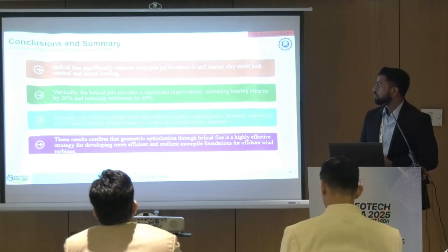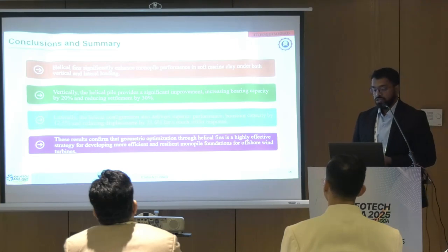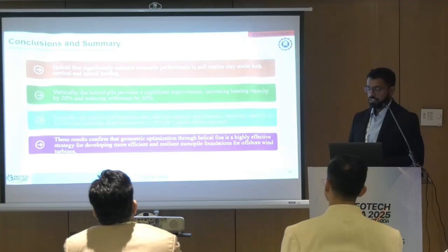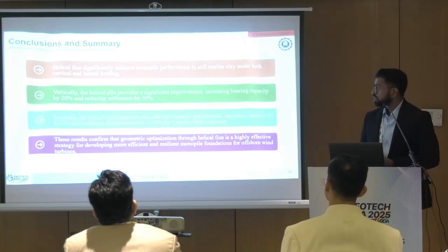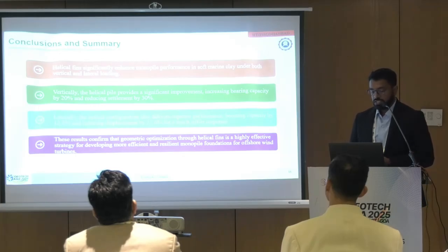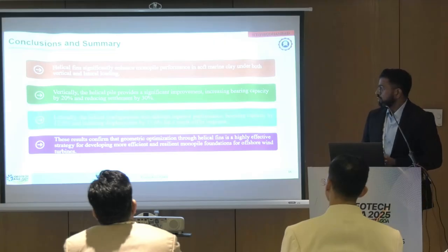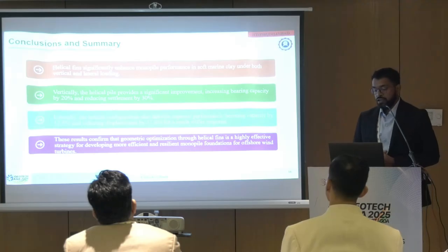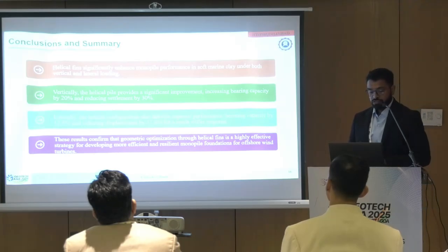2022. Coming to the conclusion and summary, helical fins significantly enhance monopile performance in soft marine clay under both vertical and lateral loading. Vertically, the helical pile provides significant improvement, increasing bearing capacity by 20% and reducing settlement by 30%. In the lateral direction, the helical configuration also delivers superior performance, boosting capacity by 12.5% and reducing displacement by 21.6%, for a much stiffer response.